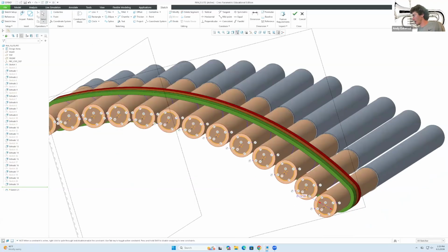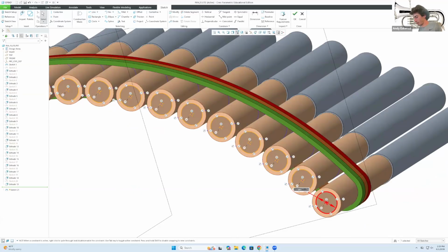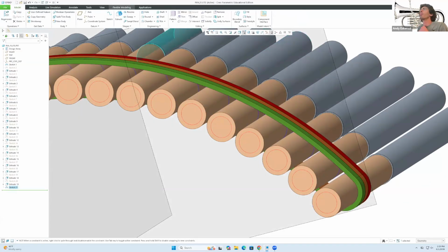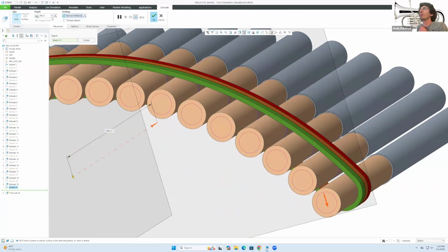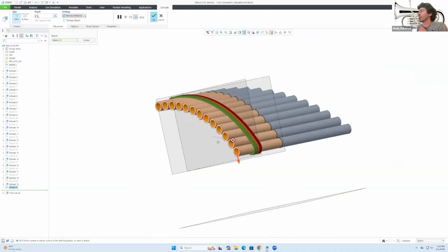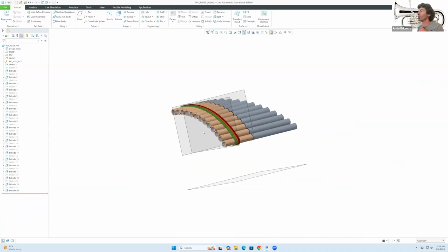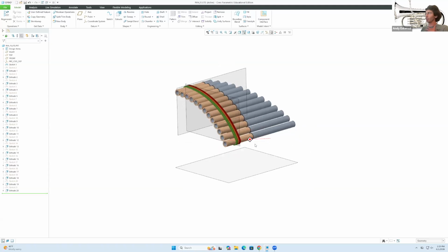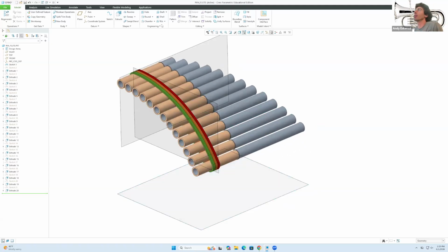There we go. And now we can say that we want our size to be 23. So what can we do with this? Well, we're gonna go to extrude, remove material, and we'll say through all. Excellent. Okay. So we're almost essentially done because the parts that remain from here are simple.